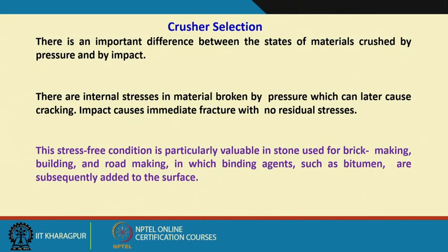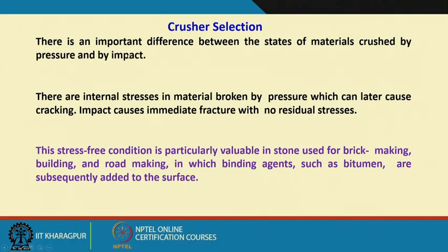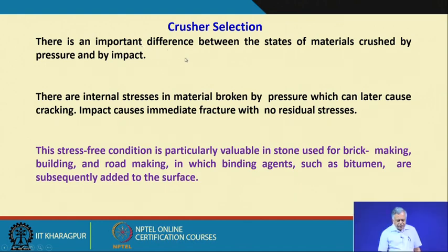So, if I look at it, we start with this fundamental difference between the crushing. There is an important difference between the states of materials crushed by pressure and by impact. That is, in HPGR we try to break the particles by pressure energy, and in other crushers mostly we try to break the particles by impact forces.